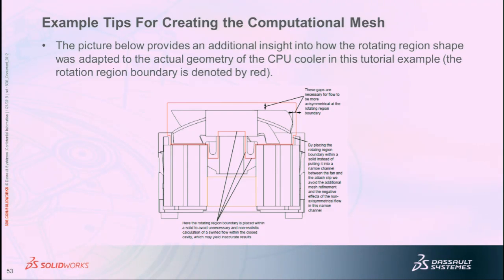I've seen people who were making a big industrial fan to dry floors of a distribution center or something. It was wet and they wanted to bring in fans. So they were actually designing these fans and they wanted to change the pitch or something of the blades. If your design intent is to do an analysis on the blade itself, then you would use the rotating option, not the fan option, because as you change the blade, the pressure drop flow rate curve would change and it wouldn't help you out.